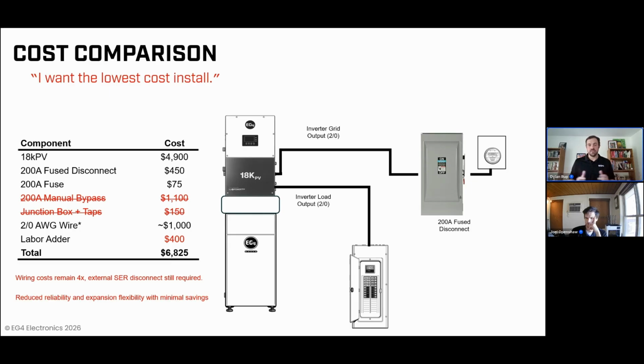None of these hybrid inverters are service entrance rated in the device themselves. It's again a physics problem. It's just too large physically of a requirement to actually fit in the inverter itself. And you might save a little bit on labor, although again, arguable that it's probably going to look pretty similar to what you have with the GridBOSS itself there.